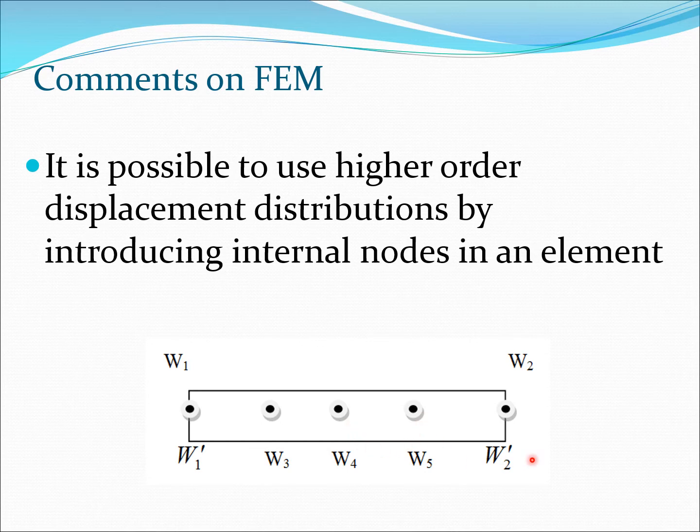degree polynomial here. Now this philosophy is the foundation of the P version of FEM, where essentially you are increasing the order of the polynomial P by bringing in more and more nodes into the system. And in fact, there are people who use P to the large extent. They may go up to 10 or 15 degree polynomial. The only problem is that sometimes you may encounter numerical issues if you use very high degree polynomials.